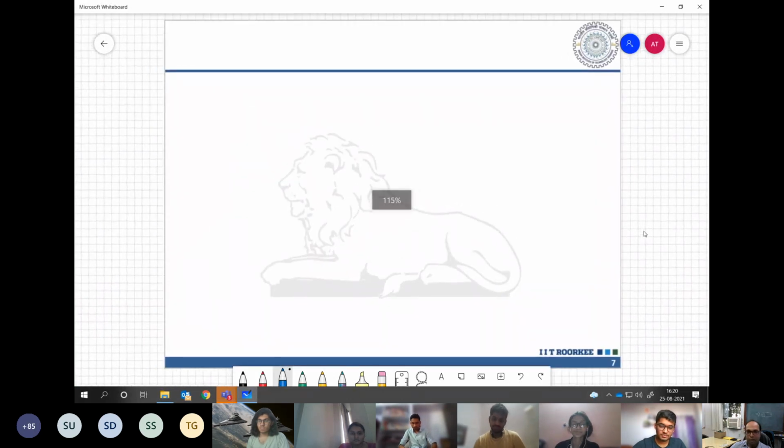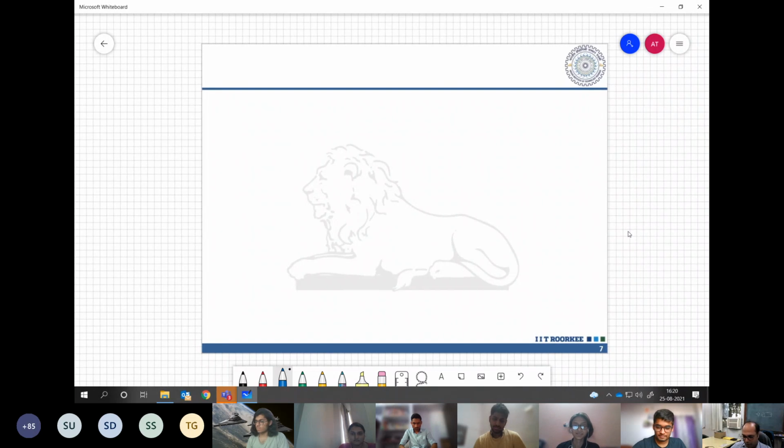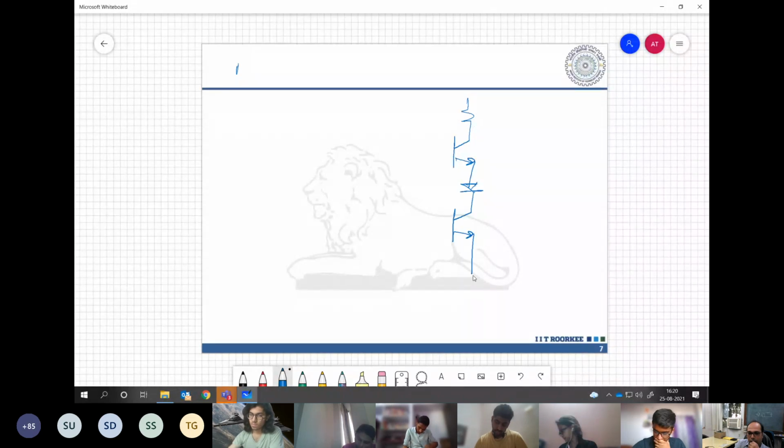Okay. Now, let us see how we realize different gates. So let us draw and then identify what this circuit is doing. So what we will have first, we will start from the rightmost side. Let's have the totem pole structure first. You need not memorize it. You can feel it, that this is how the circuit is flowing. You need a totem pole structure because there is a basic problem with RTL.